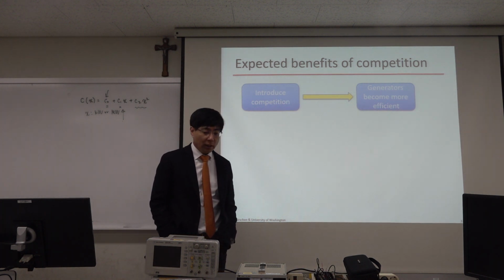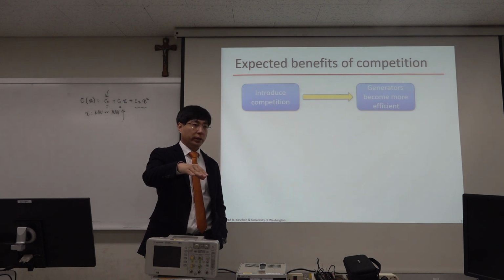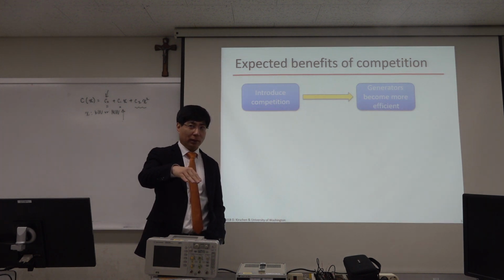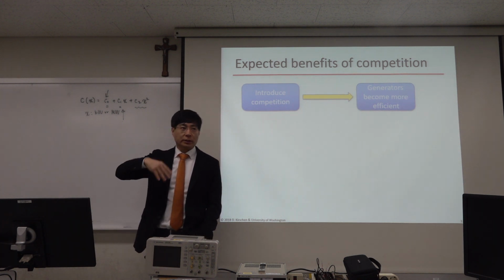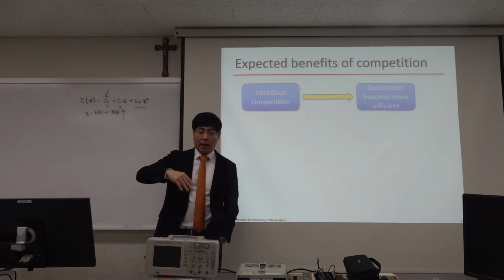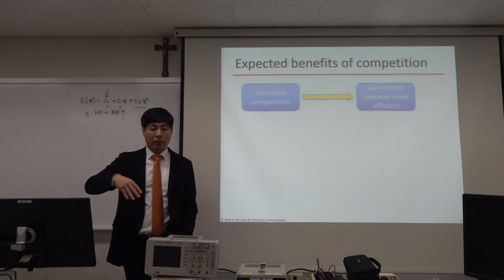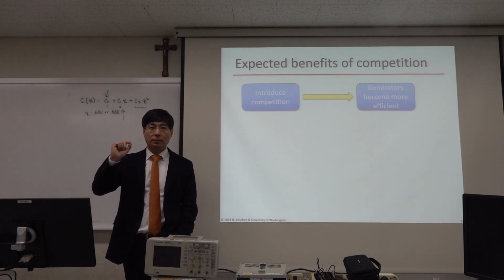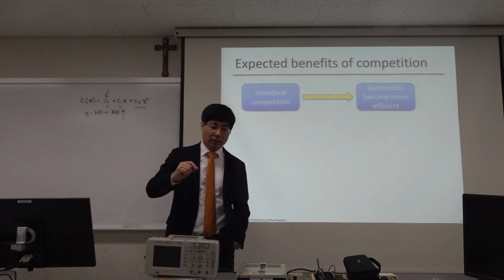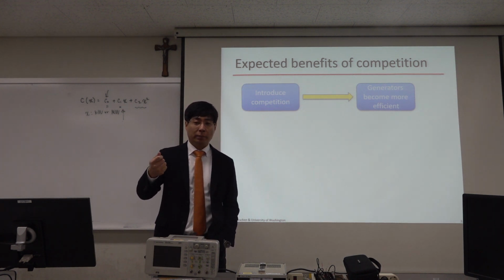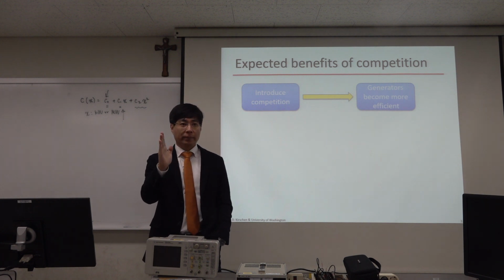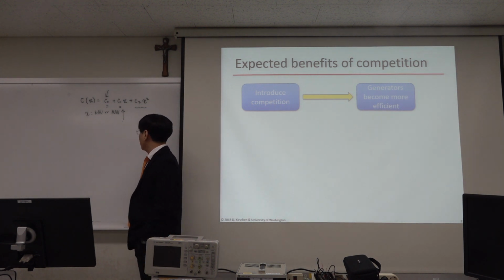So to save money, we need to turn off the generator, but turn on and off, this is a binary decision, right? And turn on and off also incurs some cost and time. We cannot expect to turn on the generator and immediately generate power. It needs to take some time. Okay? That time is called ramping time.